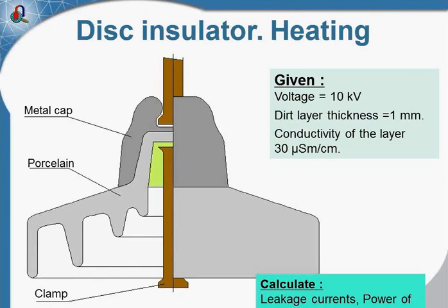You know, the transmission lines are built in the open air, so there is humidity, there is some pollution in the air that produces a thin conducting layer on the insulator surface. And if a fault could occur, the current will carry through the conducting layer.